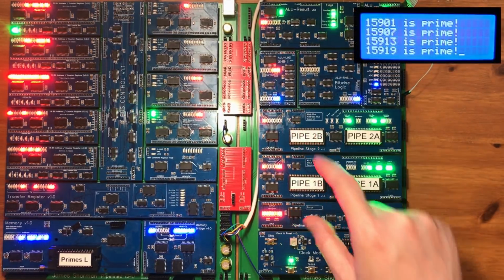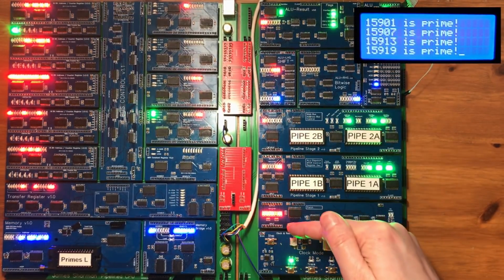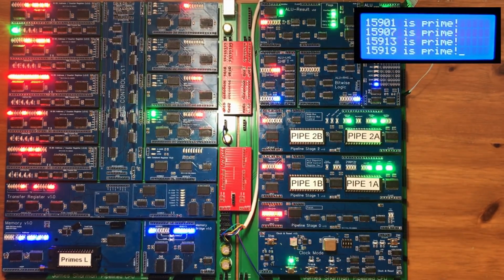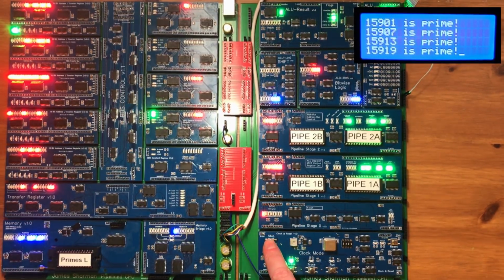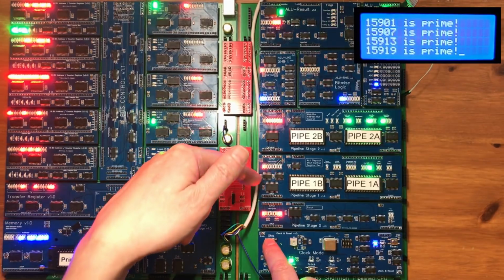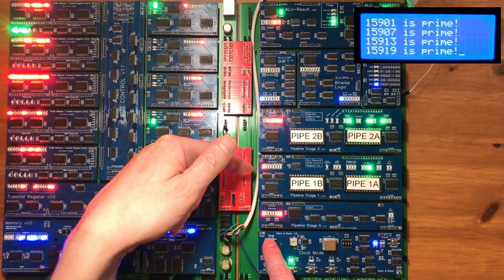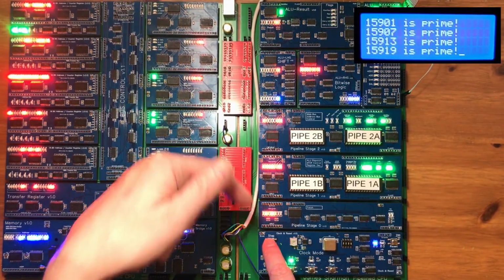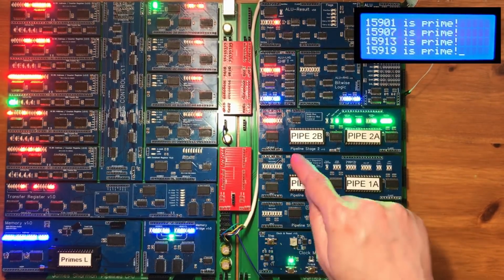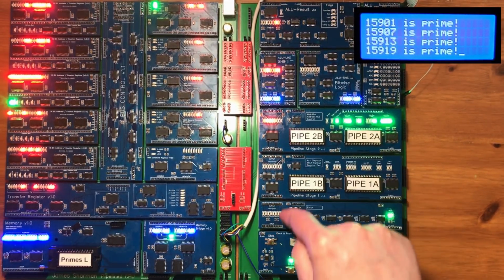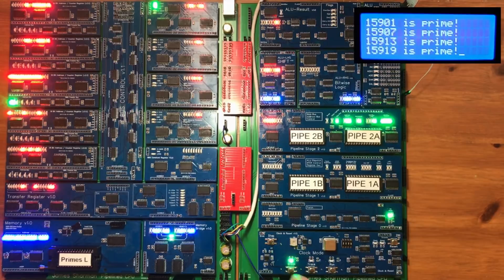Right here actually you can see I've got 3 instructions in process. If I step this along, we see that's actually a pretty common state to be in. But eventually, here we've hit a point where I've got some NOPs being generated because of memory contention. So this is a memory read operation going on because the membridge is asserting from mem data to the main bus.